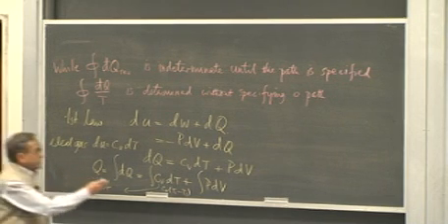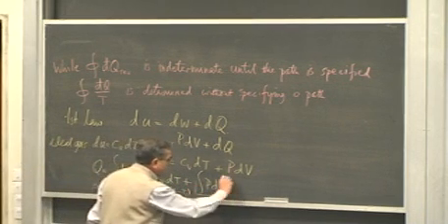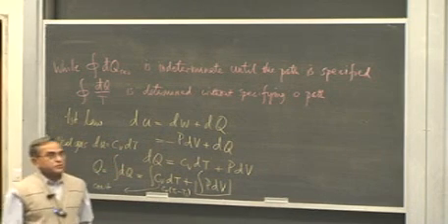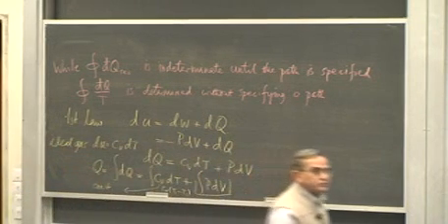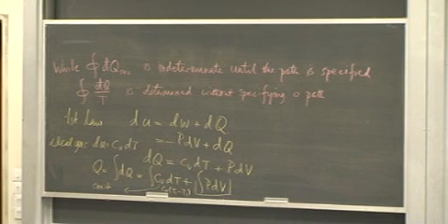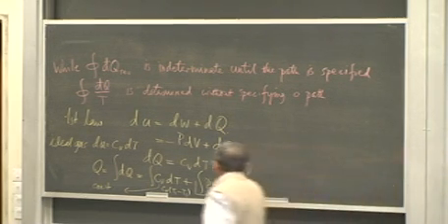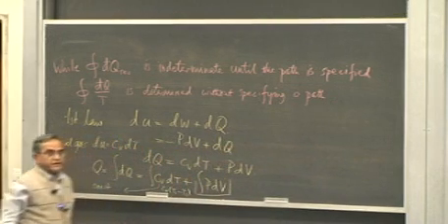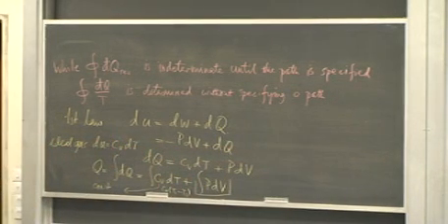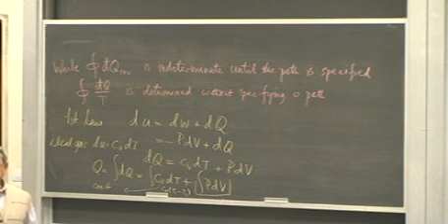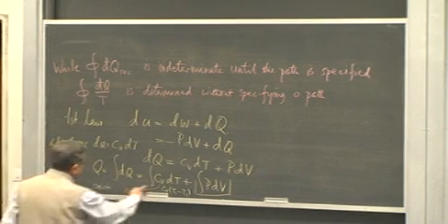But here we will not be able to do the integration unless we know a relationship between P and V. Unless we know a relationship between P and V, we will not be able to solve it. Either we say that P is constant and take P out and do the integration, which is fine. But then by saying P is constant, we actually have specified a path, an isobaric path. So we have actually specified a path over here.